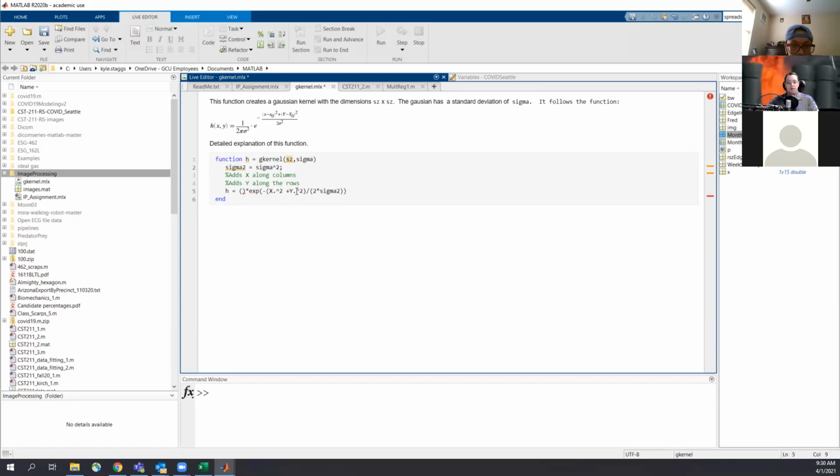That's because you're not able to multiply a vector by itself because of the way that matrix math works. So if you need the values of the individual numbers squared, you have to go through and do element-wise instead. So that goes through and squares element by element, which gives you actually x squared instead of just typing x squared, which would give you x times x transpose kind of thing, and that just doesn't work exactly.